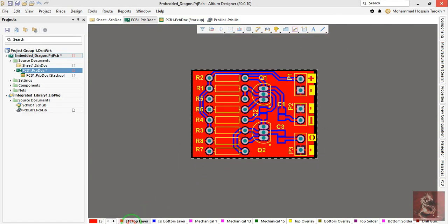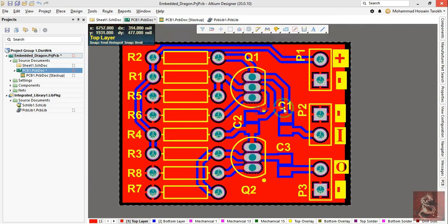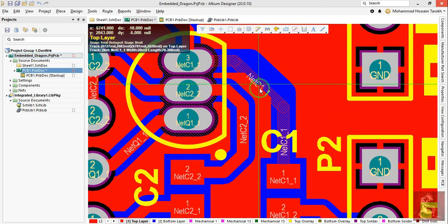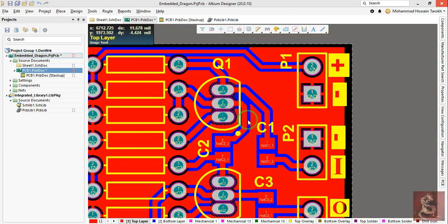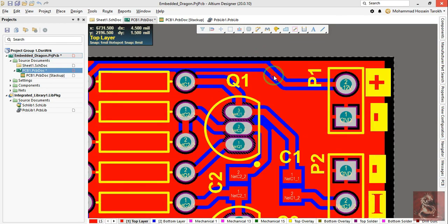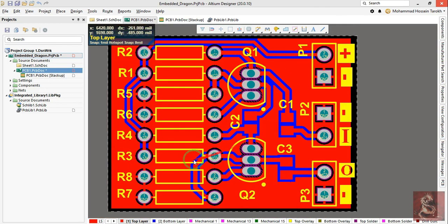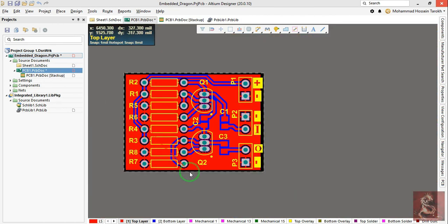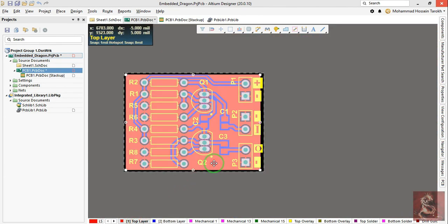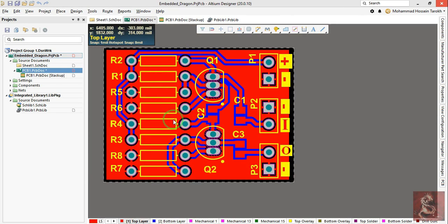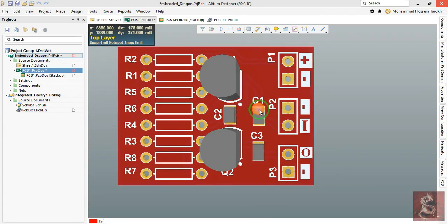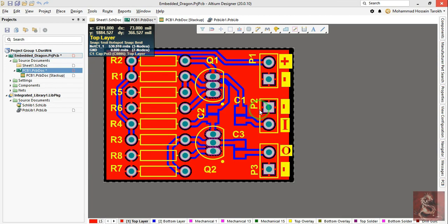So in our case, since no SMD component on top has ground connection, we actually don't require any vias to the ground. So we can easily remove this from top layer, and it's just fine. But it's not a bad idea to have ground on both top and bottom. So with this, we can say that our board, which is a pretty simplistic two-stage amplifier, is over.